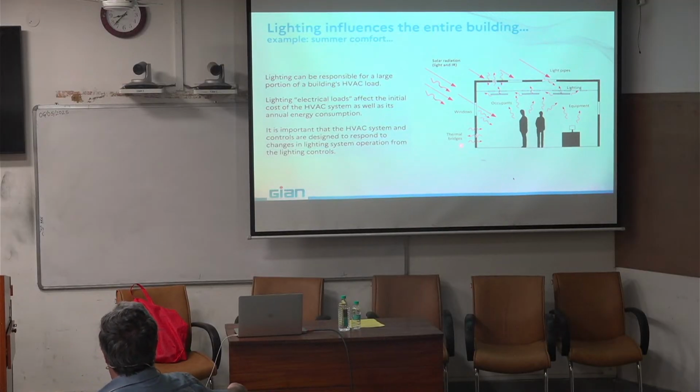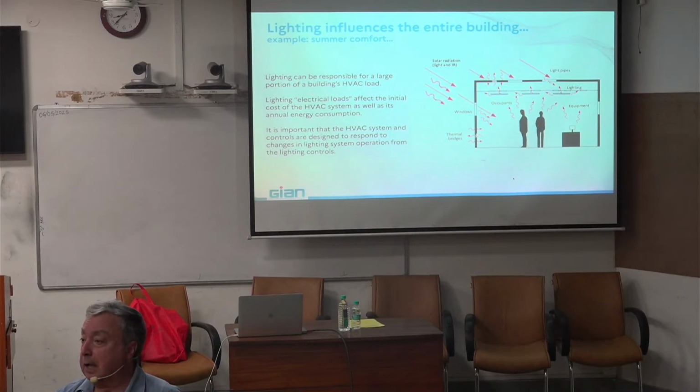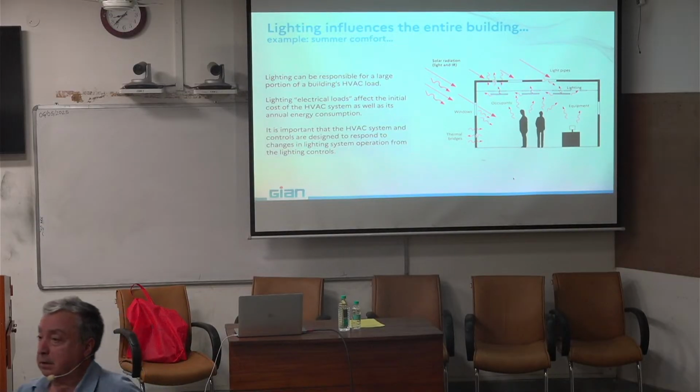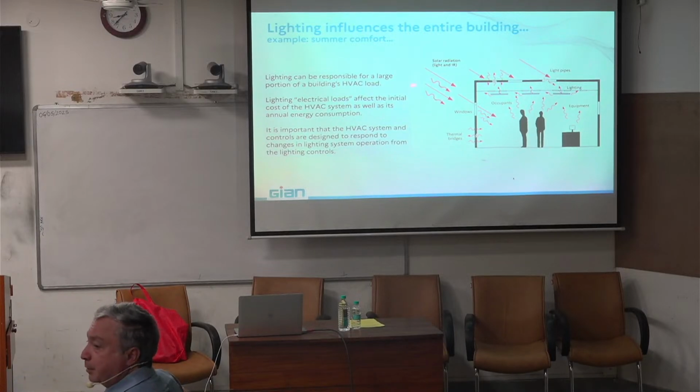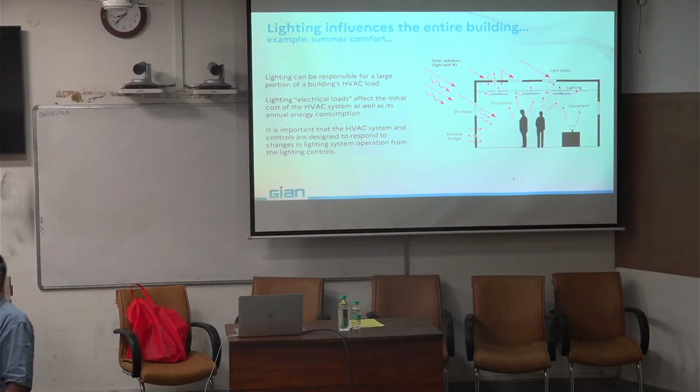If you put good insulation here, or if you put automatic control blinds, you can cut some part of the radiation coming in, and with insulation you can get also less heat coming from outside. The problem is, if you have very good insulation, if the temperature inside increases, it will be difficult also to evacuate the inside temperature. Well, globally, lighting has a lot of potential, because when you play with lighting, either daylight or artificial light, finally you impact all the other systems.